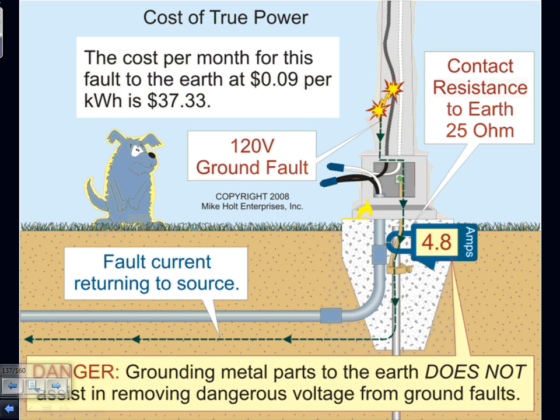70 watts, you're going to ask me, how much are we paying per kilowatt? We're paying 7 cents per kilowatt. So you're going to take the 7 cents per kilowatt, multiply it by 70 watt, divided by 1,000 because it's kilowatt. And how many hours you're going to run that baby? 10 hours. Multiply by 10 hours. How many days? 3 days a week. Or you multiply by the days, and that will give you how many dollars this piece of equipment will consume if you run it at this value, at this power factor.